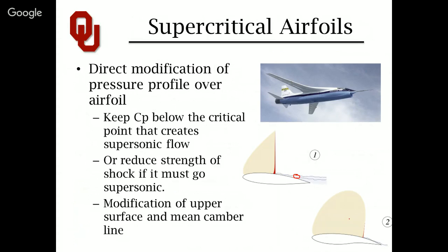The whole airplane might be going Mach 0.8. But if you're working the air, meaning accelerating it sufficiently enough, you could have Mach 1.1, 1.2 flow in certain regions. But what a supercritical airfoil does is it allows that flow to reconsolidate into a smaller shock wave at the aft portion. It keeps the camber line of the airfoil mostly neutral until the back, where you see now it kind of comes up and back down. That's a terrible drawing. I'm doing this with a mouse. You hopefully understand.